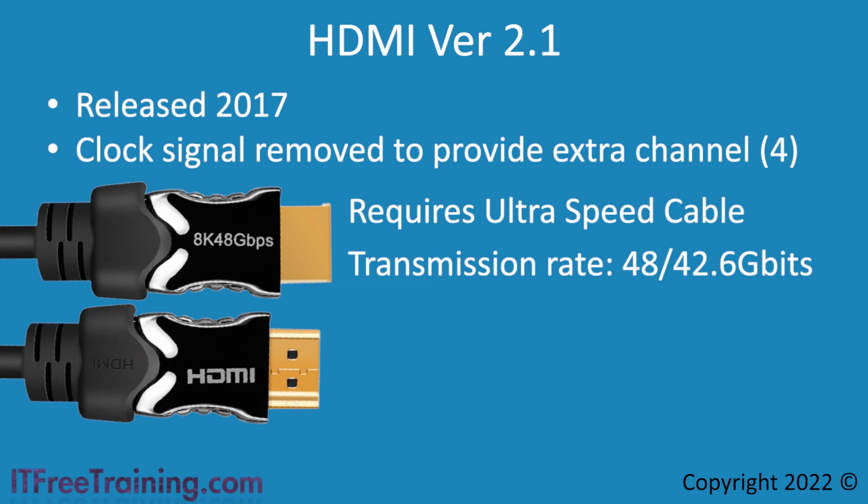In order to provide the timing for the cable, HDMI uses differential signaling, so essentially the clock signal is part of the data signal. So this is the same technology that is used for other high-speed communications like PCI Express and high-speed USB. To increase the speed even more, the encoding is changed to sending 18 bits for every 16 bits of data. This effectively decreases the overhead, meaning that you can send more data.